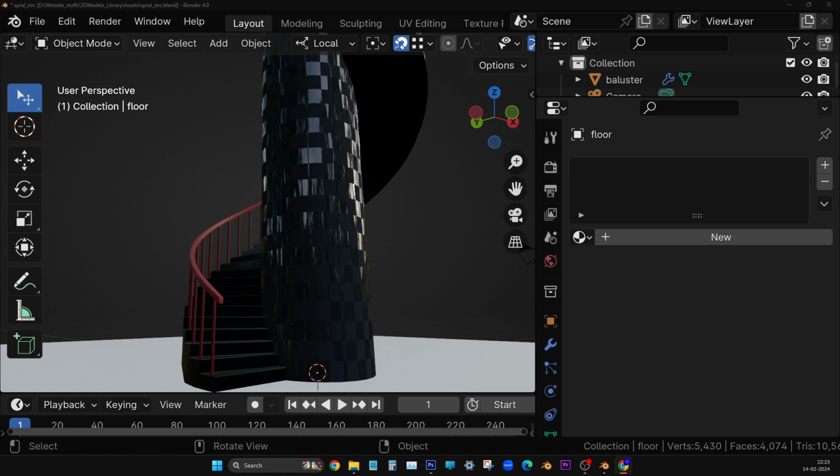Now we are going to do the UV unwrapping. So for that, select the object, select the object. Now go to edit mode. Now press any vertical edge, anything will do. It has to be in edge mode.